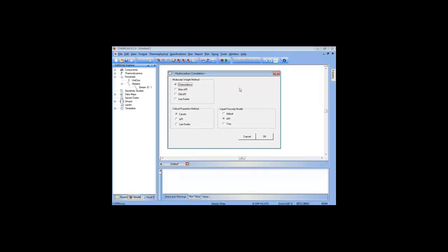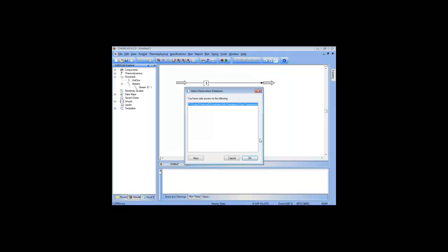It's going to use a number of different correlations. The name of this method is pseudocomponent. That's because this is a method that you would use if you were trying to make hydrocarbon pseudocomponents that are matching a distillation curve, like a D86, a TBP, a D1160. These methods tend to work decently for simple straight alkanes.